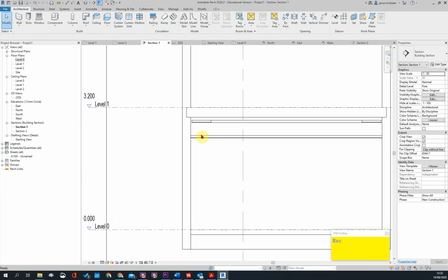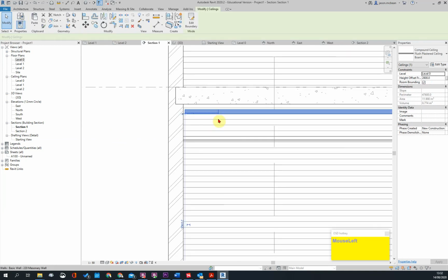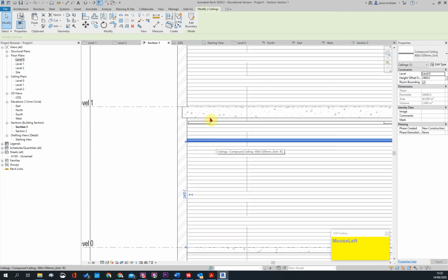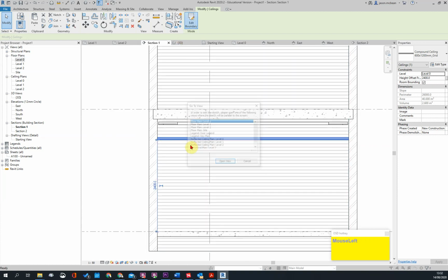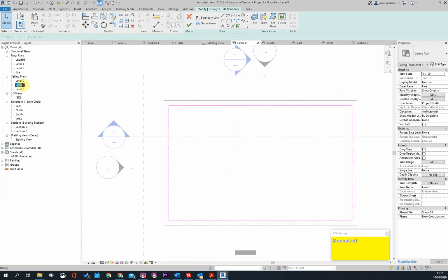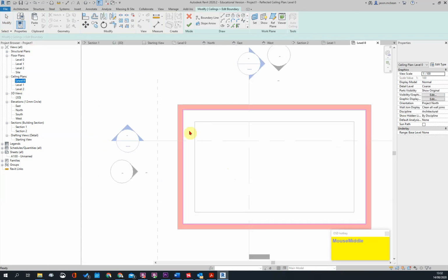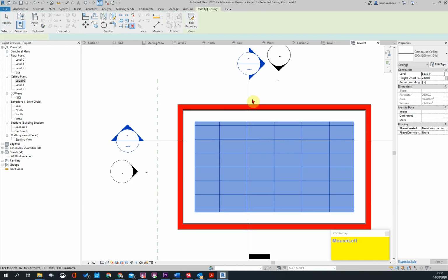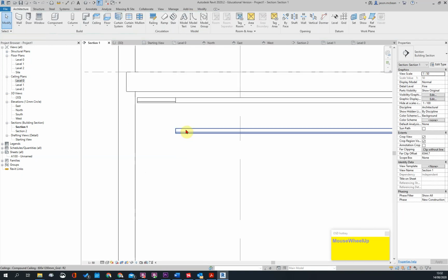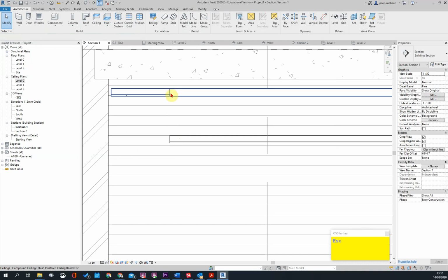I'll do the setting up now. So that's my bulkhead. So here's my suspended ceiling, my bulkhead I'll create in here. Okay, so now I'm going to use this, edit boundary, level 0. I can go to my ceiling plan 1 now, so that needs to match this line here. Get rid of this, delete, finish. So now I'm going to have a bulkhead that comes up here.